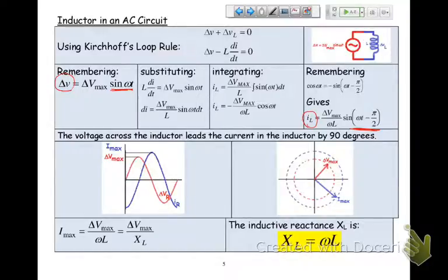I can plot it out here, and I can show this graph on an oscilloscope. That I find hard to really appreciate. This makes it much clearer. In this case, if I was to take a particular point in time, I would see that whereas this is in the first quadrant of the wave, this is actually way around here, almost at the end of the wave. So this other one is almost all the way around here. And that's how you get these two shapes.